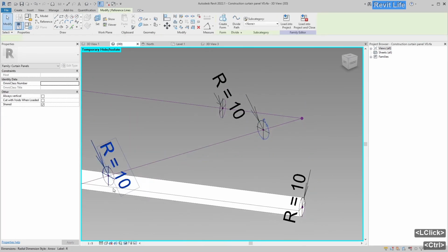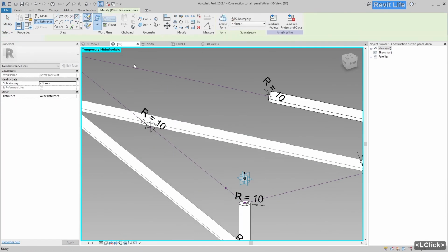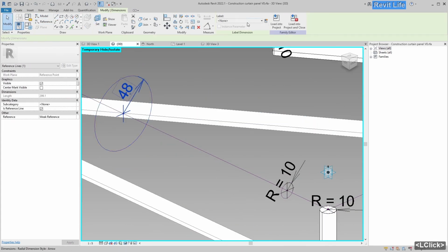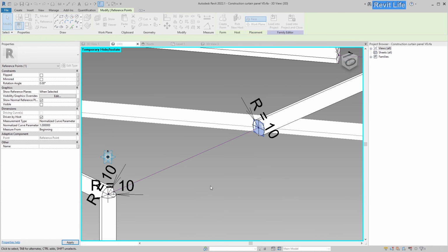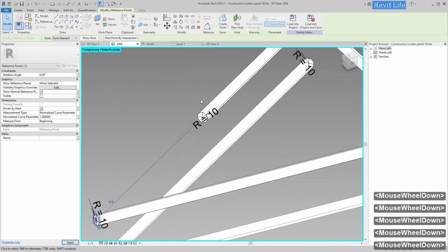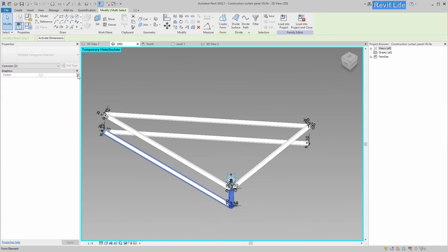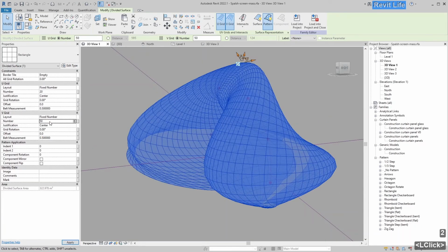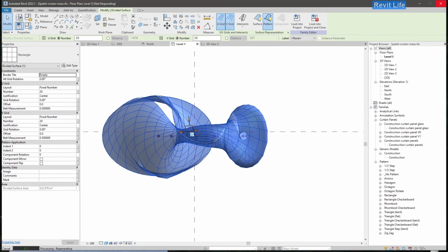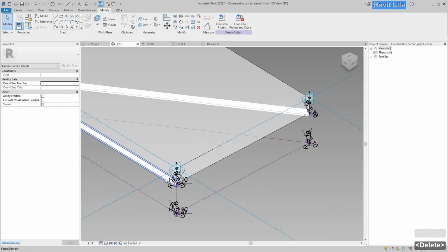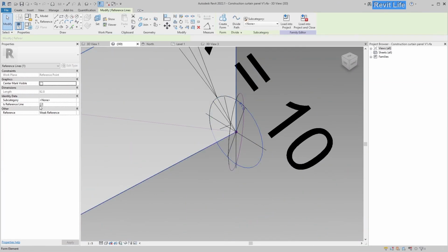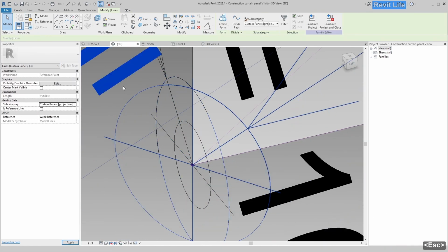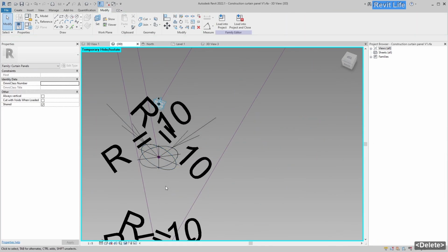And here you can see my first try to use two profiles for the pipe. It works in the way that it changes the radius of the pipe, but when I try to populate the surface with this family, it throws a bunch of errors and it doesn't populate the whole divided surface. And yeah, here you can see that I delete all of the pipes and I try to make all of those pipes again with the beginning and the end profile.